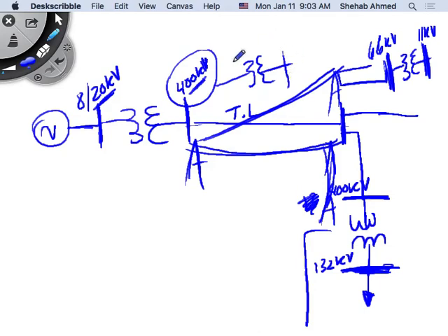Yeah, but before that, actually there's a 400 to 200 typically, because we have a 200 kilovolt network. So some people will be taking power at 200 kilovolts. And then there is a 132 kilovolt network in Qatar. And then from 132, I will typically have a transformer from 132 to 66. That's before this one that's in the building behind city center, right?